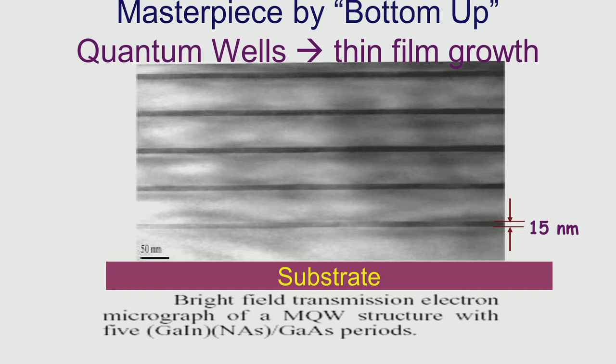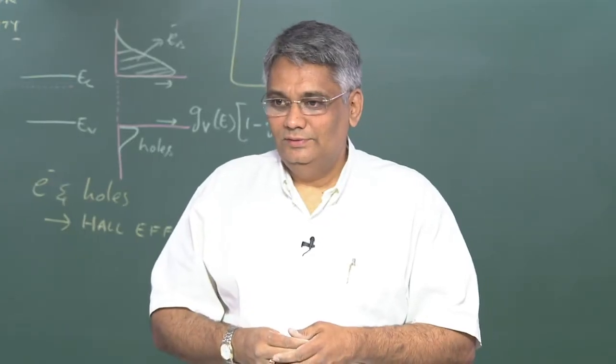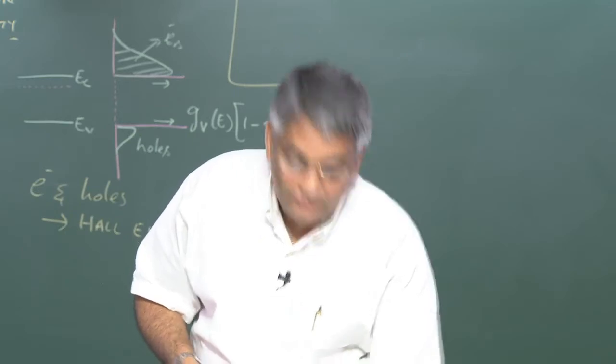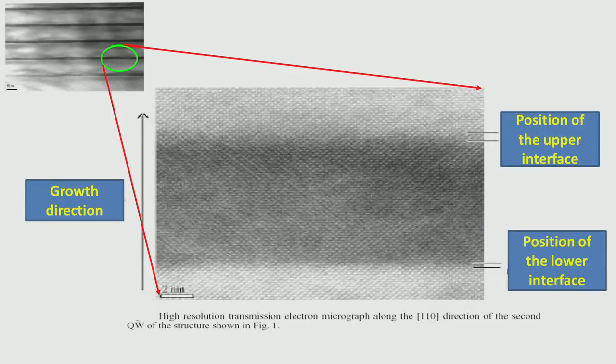See, the interface here plays a very crucial role, right? Because especially when you are growing structures of 2-3 different materials, there is no guarantee that crystallinity exists at the interface. And how do you look at that? So you need high resolution electron microscopy. So I just expand or magnify this region and see what you see here.